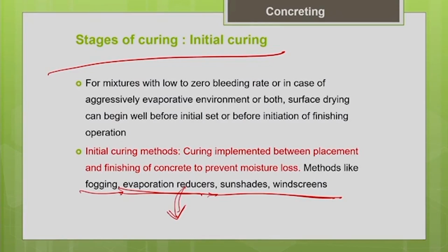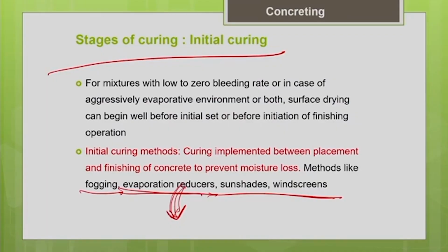And one demerit of the evaporation reducer is it may sometimes leave some stains on the concrete surface. That is one disadvantage. And it is preferable to apply this evaporation reducer when the concrete bleed water is already there on the surface. So, before the concrete dries, when the bleed water is there, at that stage itself you have to spray the evaporation reducers. That is the best way to apply it.